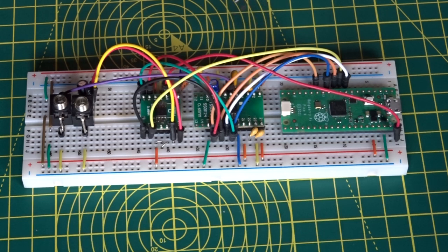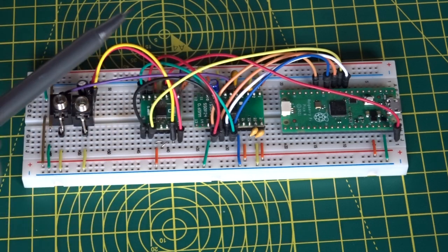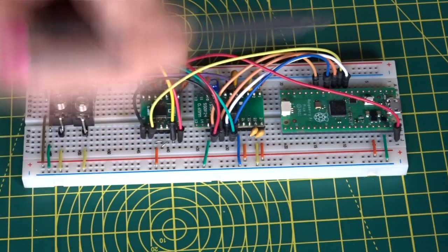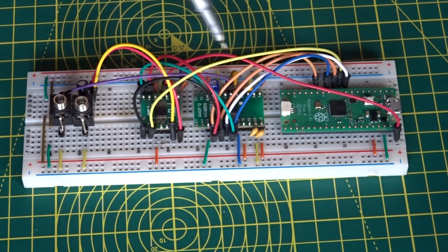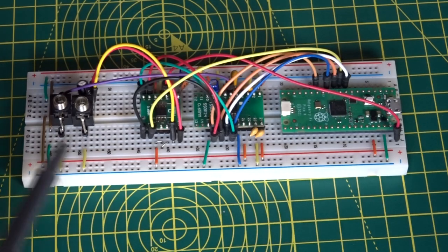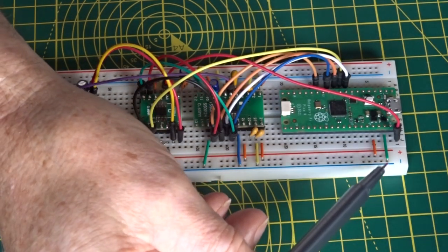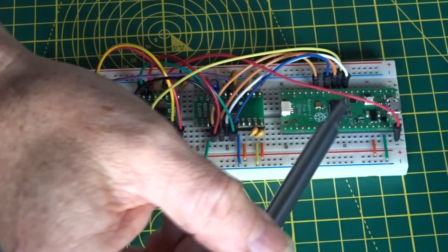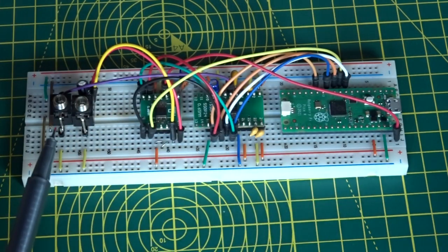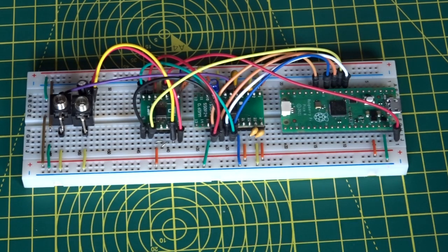The rest is exactly as per those example circuits. So these are the signals out from the Raspberry Pi Pico, and they're all kind of paralleled across, apart from data out goes to data in, and data in comes from data out, and then there's a sprinkling of capacitors, various things tied to ground. I'm picking up the ground from the Pico and the 3.3 volts, and this is the 5 volt across to the 1808, and that's about it. So we'll plug that in and see if it works.